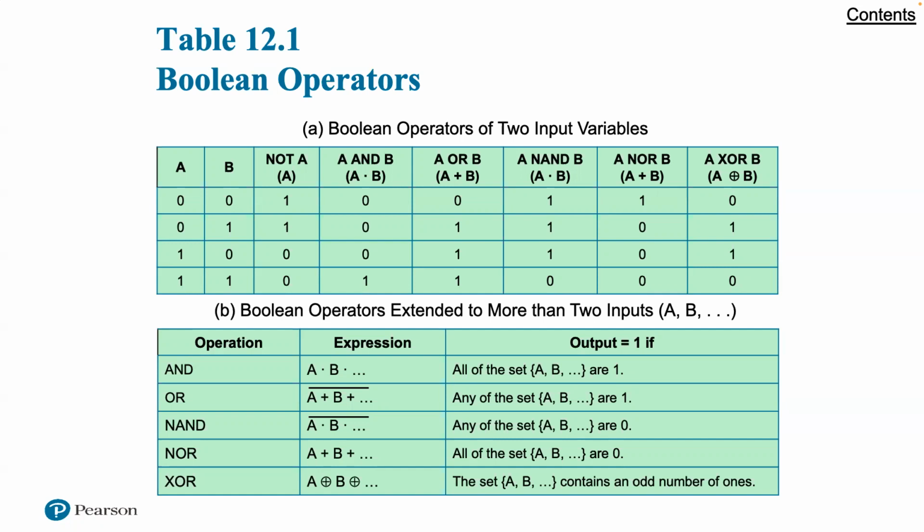The exclusive OR, XOR, of 2 logical operands is 1 if and only if exactly one of the operands has the value 1. The NAND function is the complement, that is NOT, of the AND function, and the NOR is the complement of OR. As we shall see, these 3 new operations can be useful in implementing certain digital circuits.